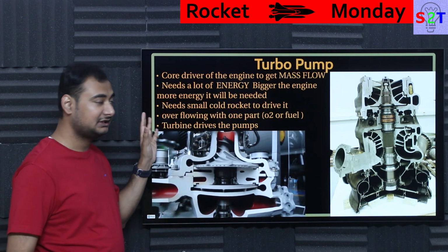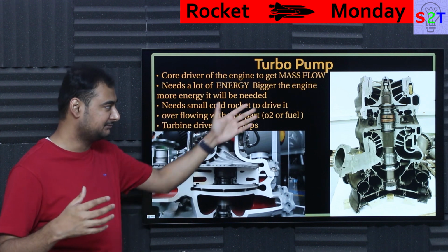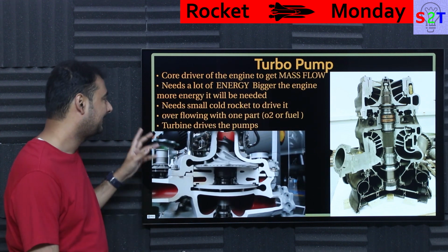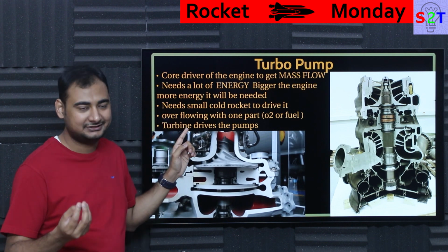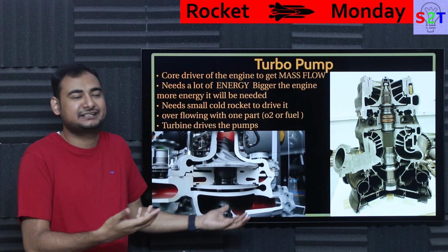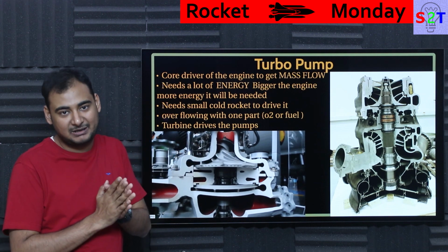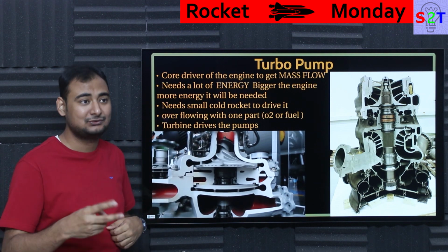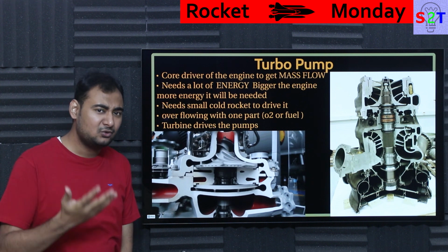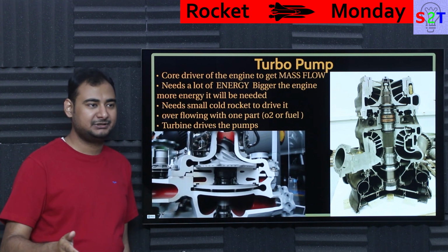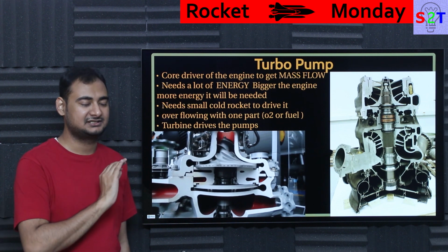So there is an upper limit, basically unless you can make the pump as big as you want to, you can't really flow a very large engine. Now it does need a rocket to drive this, because again, where the heck are you going to get like 20 megawatts? So for a small one, Rutherford does try batteries, but thankfully it only has to work for 2 hours, and the power requirement is low enough where modern lithium ion can touch it. But the moment you go any bigger than that, yeah, no, thou shall say no to it.